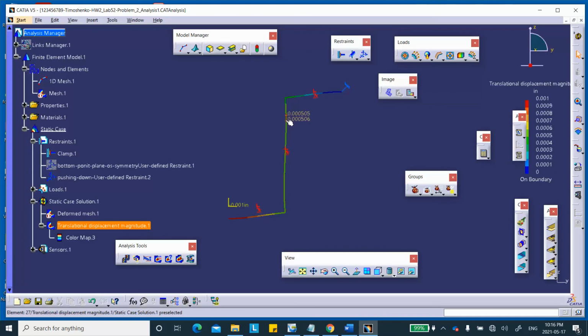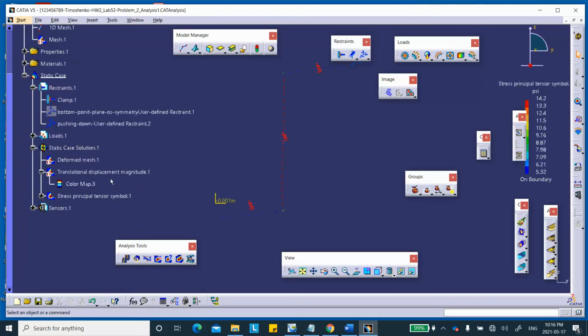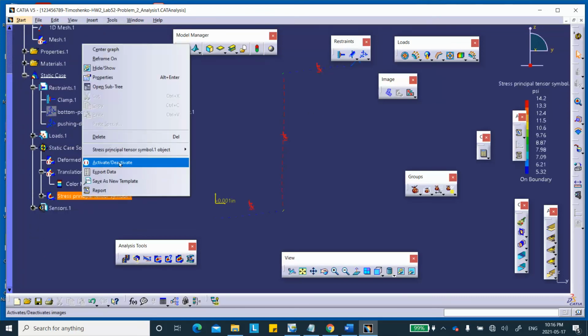It will say that, hey, listen, I can't do it because I'm kind of weak in the beam element type thing. There are some other packages which plot the von Mises stress at a specific location, which is already predefined, or you can declare it. But anyway, CATIA won't do that. It will plot for you the principal stress, but unfortunately, the only principal stress that it can plot is the axial one, which is kind of totally useless. Again, the reason it won't do that is because principal stress also depends on the location at the cross section. So deactivate this, no problem.